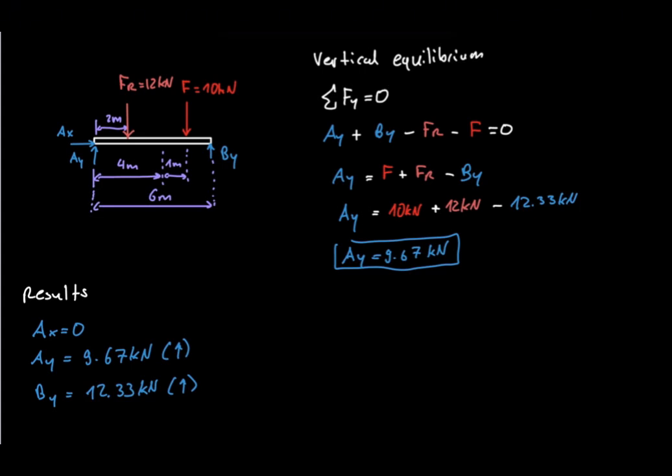The most important lesson is that mixed loads do not require a new method. First, replace the distributed load with an equivalent force. Then solve the problem exactly as before. Once you learn this workflow, even complicated beam problems become manageable.